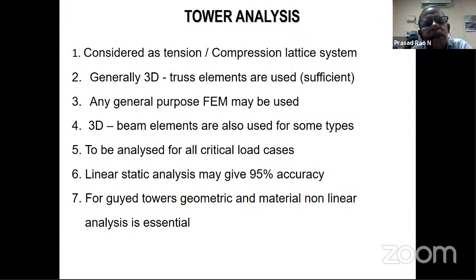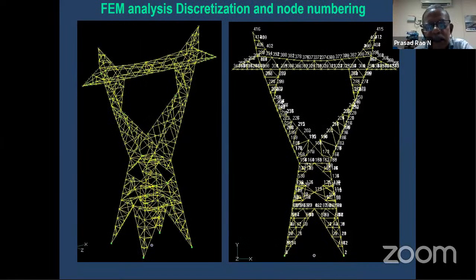So this is a typical model of a transmission tower. This is taken from Nastran. We are using Nastran modeling, and here we can model all the secondary members. We can see by doing nonlinear static analysis, we can find out the forces. Now coming to transmission tower, the communication towers.